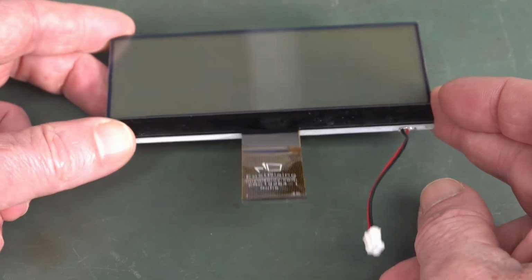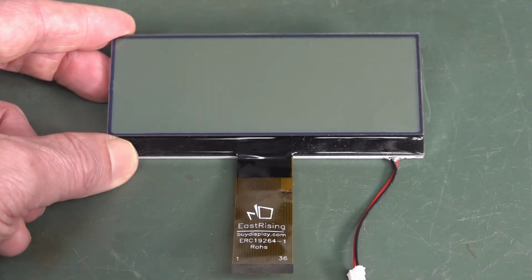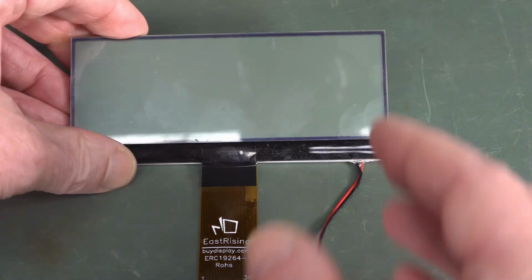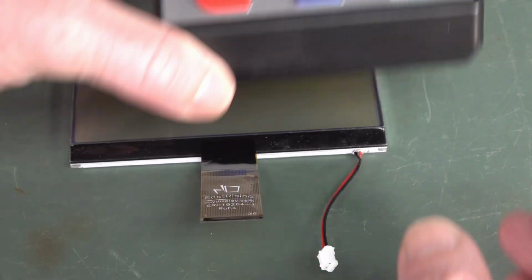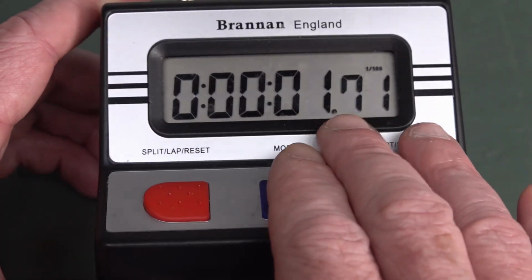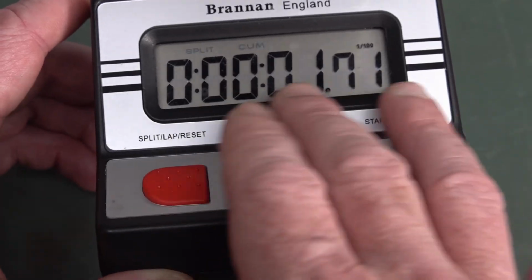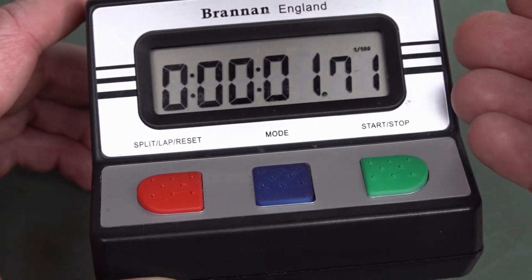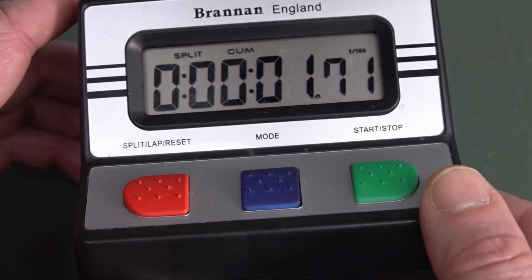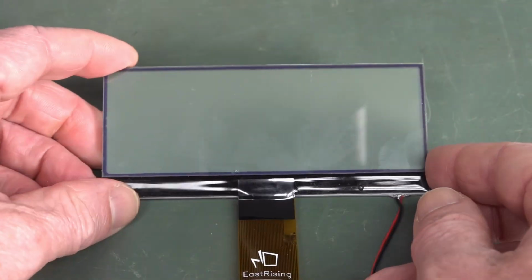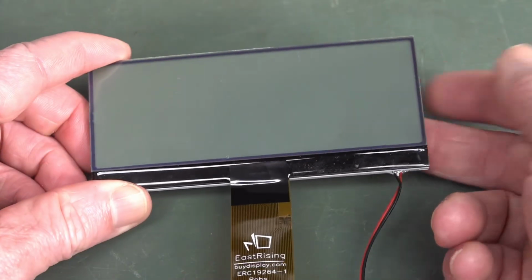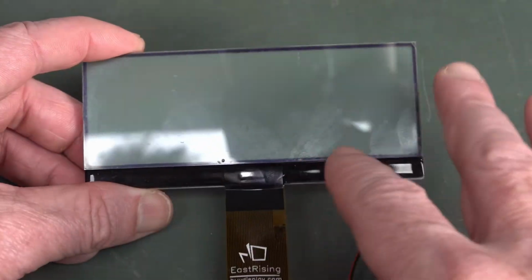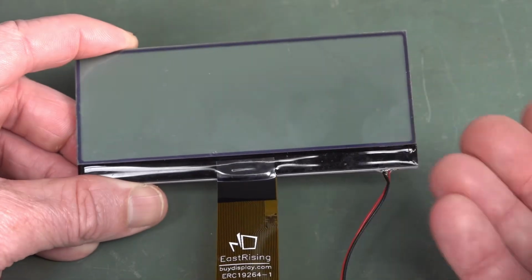Now, it does include a backlight on here, but this is what's called a transflective display, and I think I've done a tutorial video on LCDs and the different types. Transflective means that it combines the best of a reflective, this is a 100% reflective LCD, like you don't need a backlight, it doesn't have the ability to have a backlight, it's 100% reflective backing on it. So that's called a reflective LCD, and this one is also reflective, but it's transflective in that it will also allow a backlight through, and this one does come with a nice white backlight on it, where it allows the light to come through.